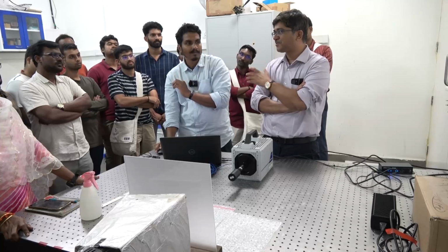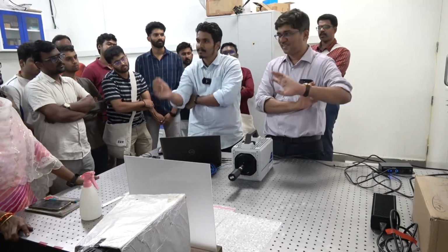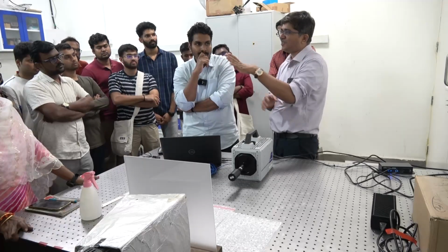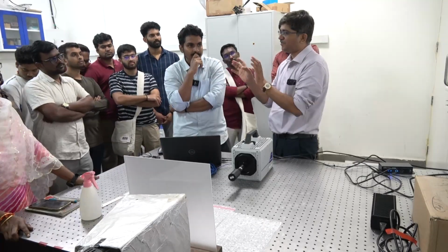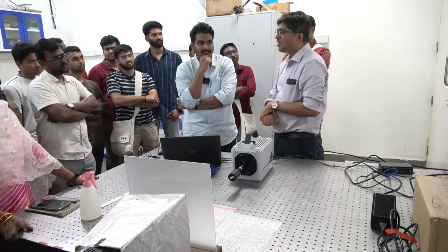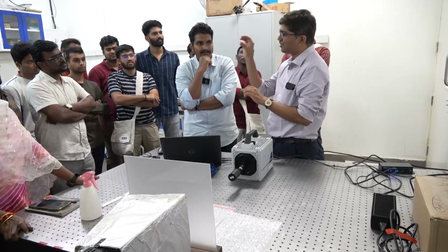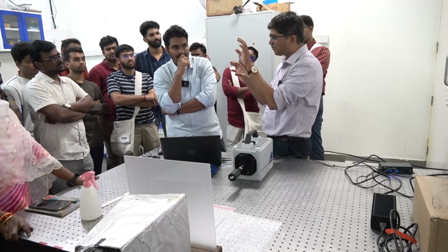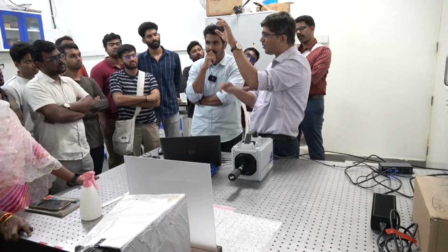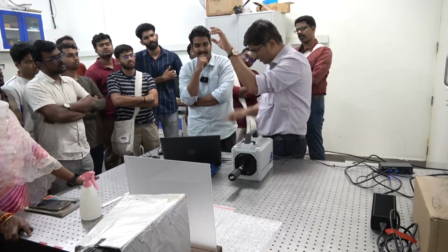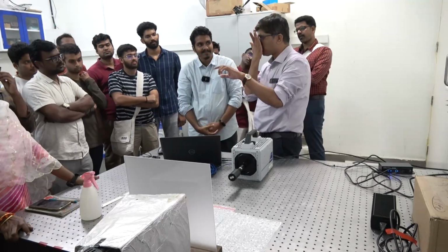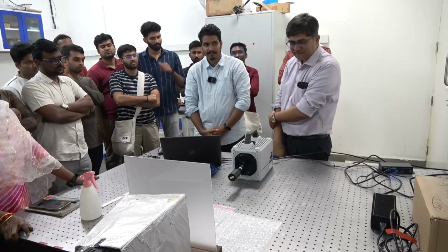The maximum expected movement is mentioned there. Different drops will have different velocities, but this is the maximum distance any drop can move. Otherwise, if you have similar drops of two sizes, one moved here and another moved there, and you don't give this maximum cutoff, it may map this one to that one, which gives spurious vectors.